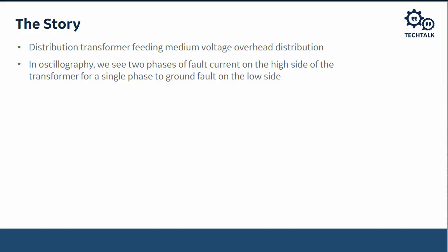And medium voltage distribution systems are subject to things like lightning strikes, tree strikes, and squirrels who can breach across the insulator and cause a phase to ground fault. And so medium voltage overhead distribution like this has faults, and there's typically a reclose that takes care of that, so it's not that big a deal. But explaining this particular event was sort of puzzling.